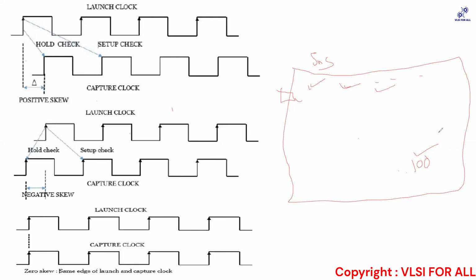Now look at the concept of power dissipation, which I covered in the demo lecture at the start. You would have understood that the major contribution in your design is the dynamic power dissipation. And when you looked at the formula of dynamic power dissipation, you know that it depends upon alpha F C VDD square. Okay. Now look at it.